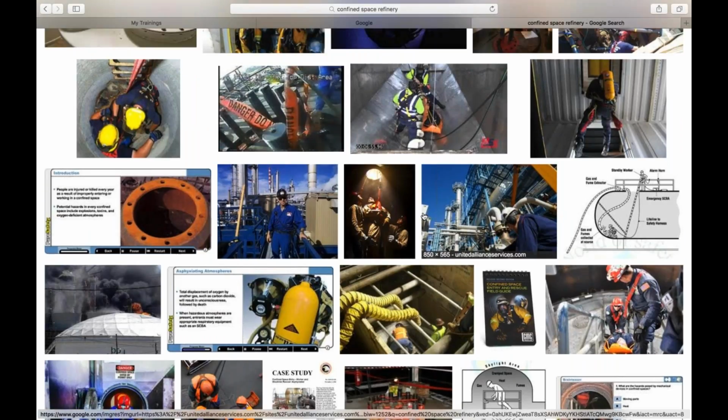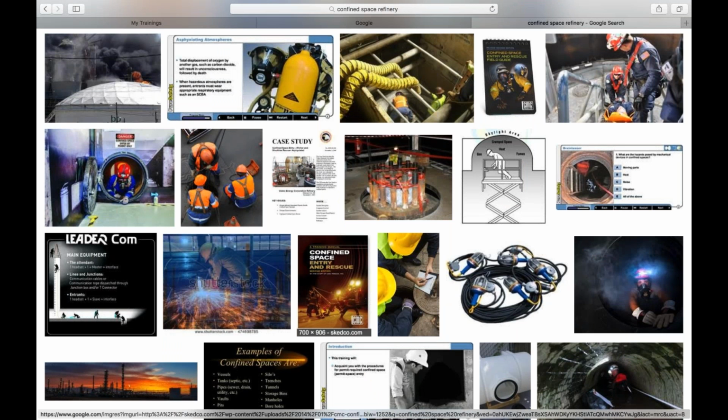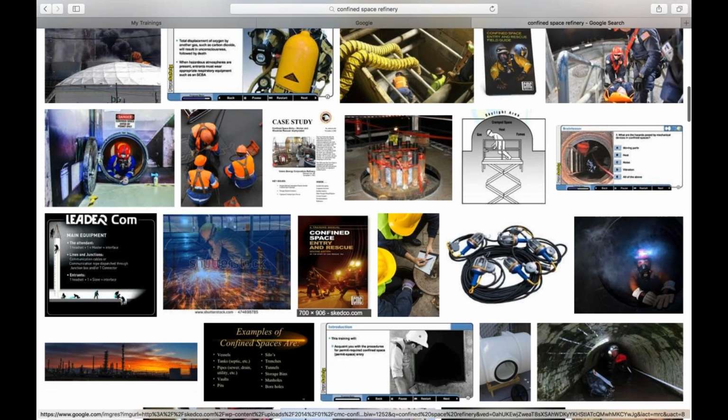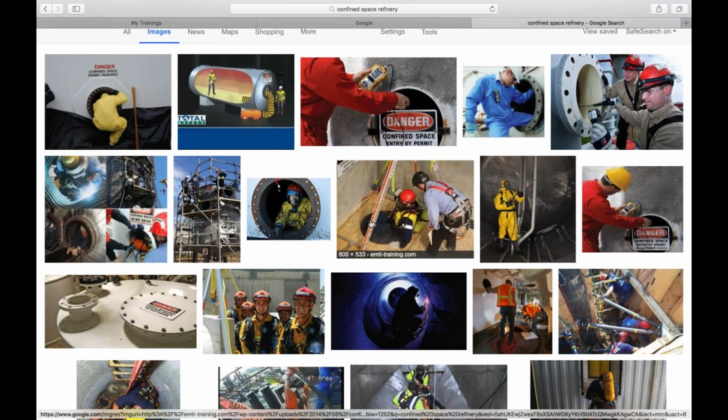Okay. Also, employees must wear appropriate personal protective equipment, right, when entering the vessel. Mandatory use of safety harnesses should be stressed. So if they're going in vertical, especially vertical, but even horizontal, we want to have a safety harness. The reason we want to do a safety harness is so we can do exactly those retrievals that I just showed you right now. Okay.